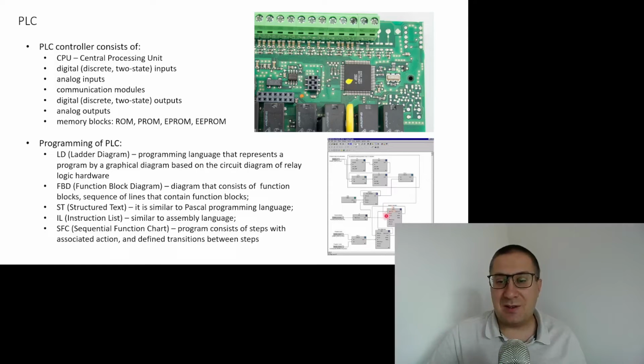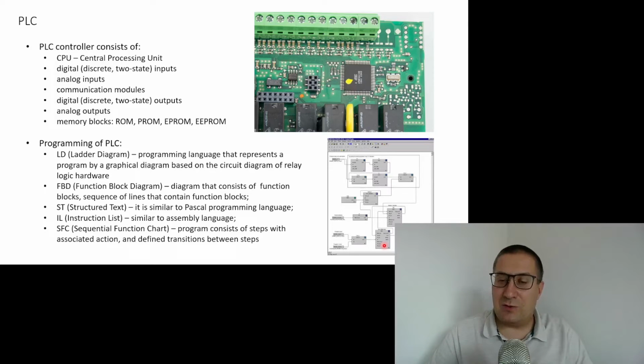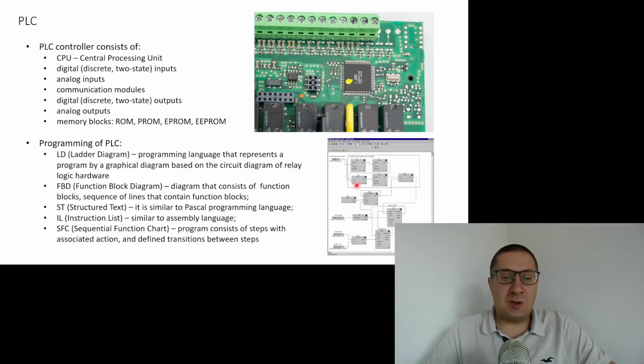It consists of, for example, two PID controllers in a cascade. One PID controller calculates what should be the set point for the secondary PID controller, in this particular case the set point for feed water flow. There are also some gains, some limits, some denoising blocks that we can use.